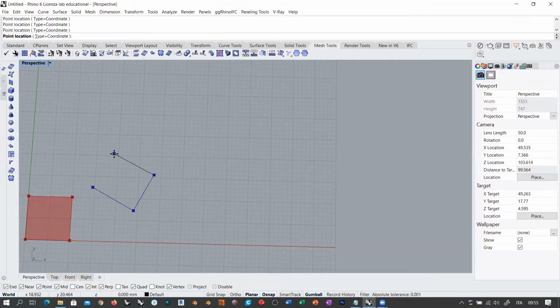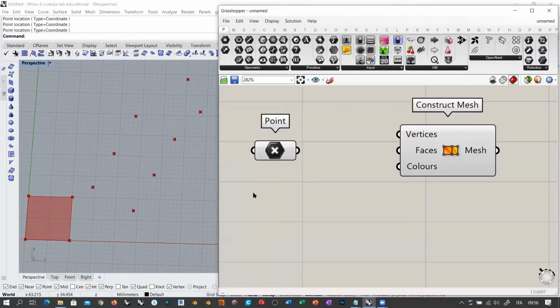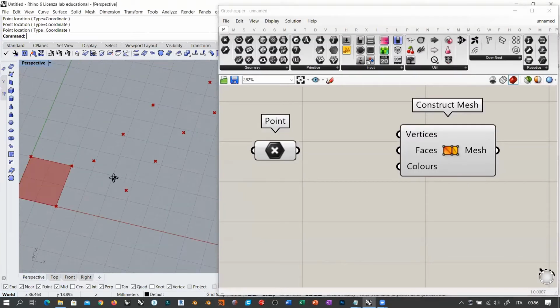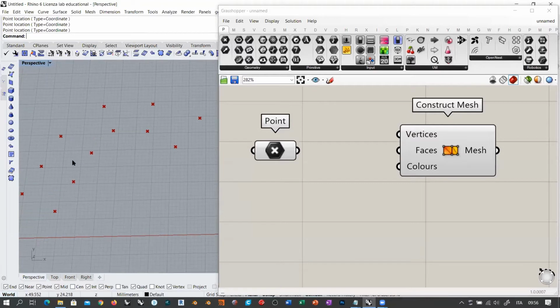And now what happens when I have, for example, vertex 5 and 6? Because I don't need other vertices. I don't need another vertex here and another one here. I just need this couple here that will be connected via the face connection scheme to this vertex and this one. And then I eventually need this one and this one and this one and this one and this one and this one. Okay, so these are going to be the two lines of points that I want to use for creating the mesh. And I plug them here.